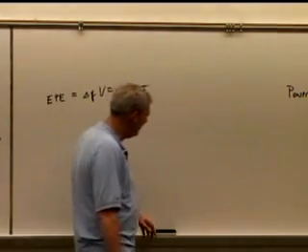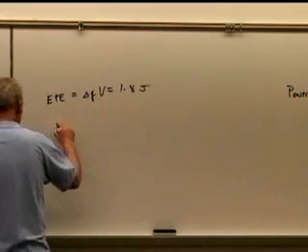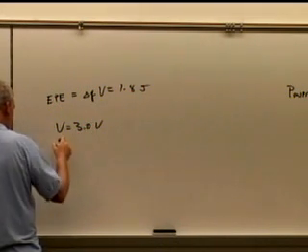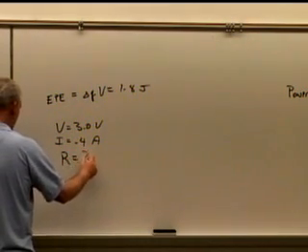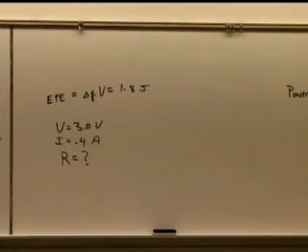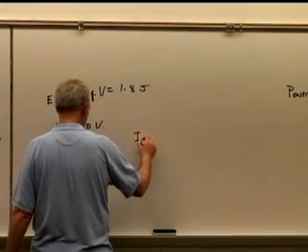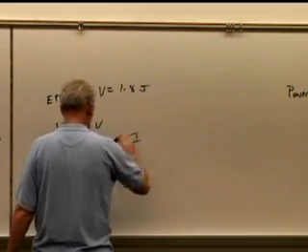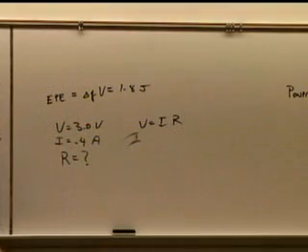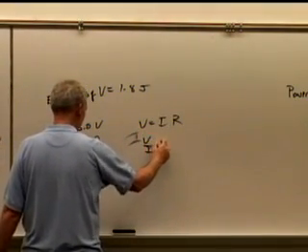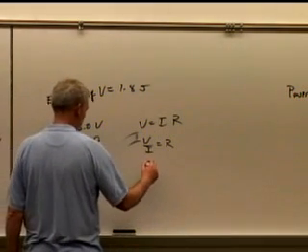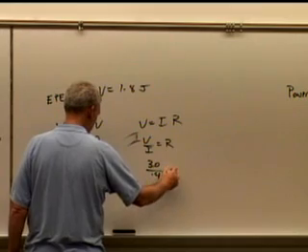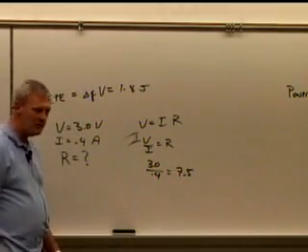All right, so we're going to determine the resistance of the glowing filament. We've got V equals 3.0 volts. We've got I equals 0.4 amps. Okay? And now we need R. We need the resistance. So V equals IR. So V over I equals R. Did I do it right this time? I'm gun shy now. So I get 3.0 divided by 0.4, and that equals 7.5. Oh, ohms. Here it is.